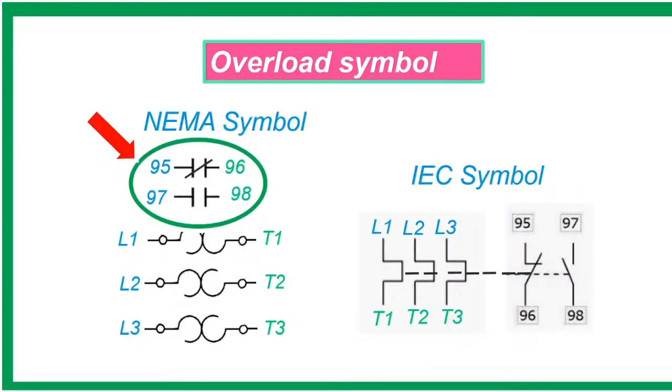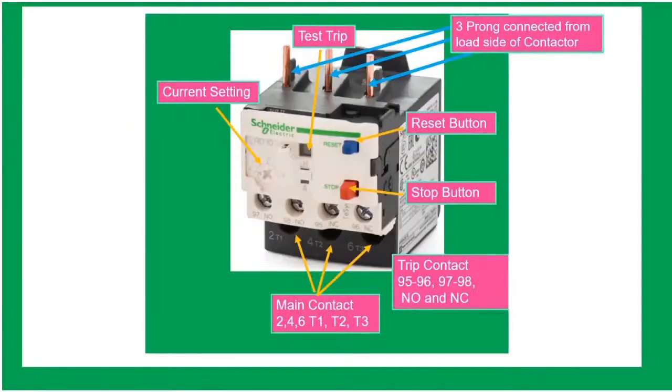An overload relay also includes one or more normally open and normally closed contacts. These contacts are connected to a pilot light, buzzer, or alarm light to warn the operator or maintenance. The overload relay is always part of a magnetic contactor and is designed to protect the motor against prolonged overcurrent. This means if the motor runs for too long with high current, it will overheat and destroy the motor. One of the causes for this is a bad bearing.